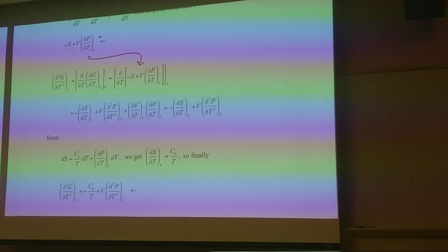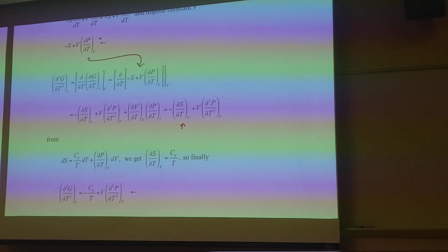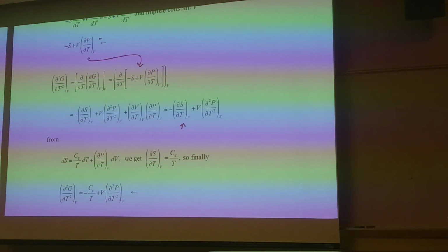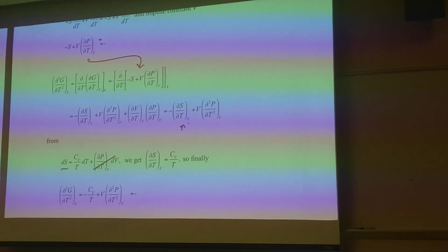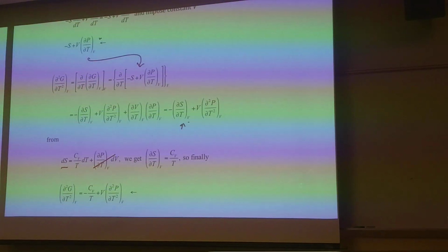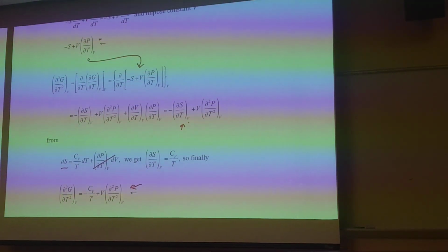Well, I see it here. There are a number of ways you could do that, but the quickest way I think is just to build it out of the expression I've got for ds here. This is a constant B, so I see right away that term goes out and it's Cv over T, and I can just get it by inspection. And end up then with this result.